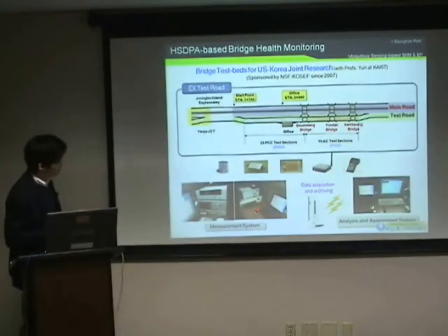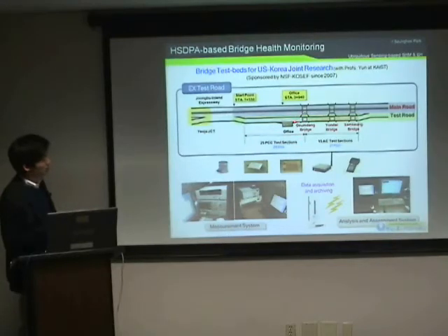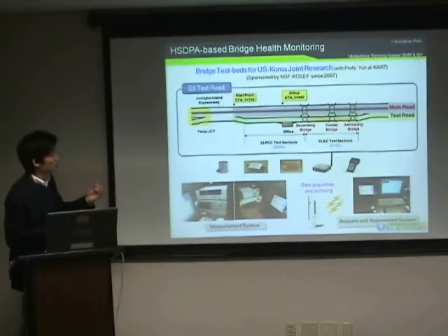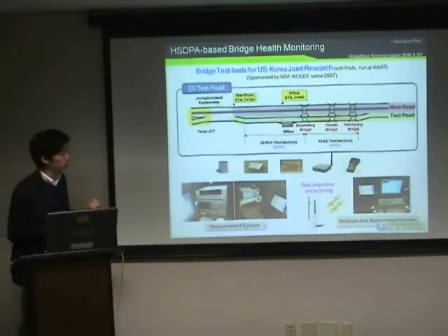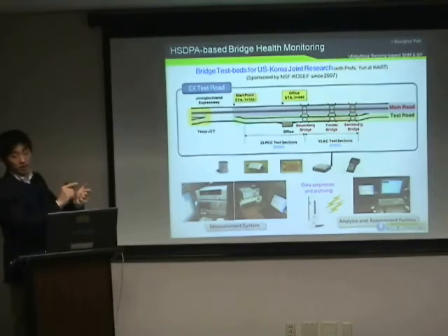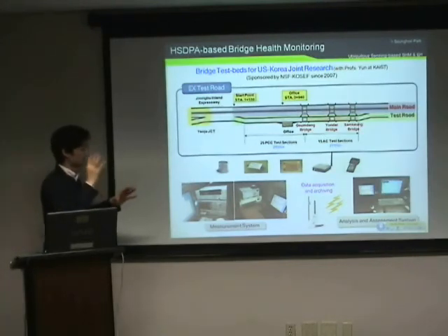Okay. Here we go. Their measurement system is installed into Geumdang bridge here. We can implement this mobile telecommunication system for data acquisition and archiving. So we can see real-time data, including accelerometer, strain data from fiber optic sensors, impedance and wave data from piezoelectric sensors, by using our smartphone. So by using our smartphone, we can see real-time data from the bridge. So we can check what problem or what condition the real bridge structure has.